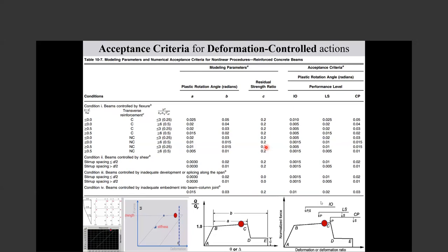If you are using analysis based on modal analysis and its mass participation ratio as per code cannot be satisfied, how can we solve the problem to perform nonlinear analysis? There are two points. One point is methods for doing nonlinear pushover for different cases where ordinary nonlinear pushover analysis is not applicable.